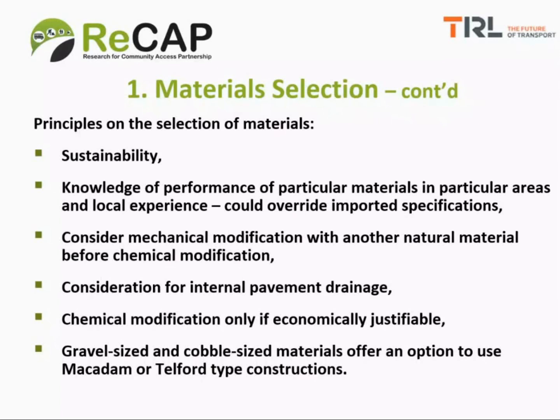And the third principle to bear in mind is that often if your materials do not meet specifications, please consider mechanical modification with another natural material before considering chemical modification. And the fourth principle is that where possible, consider the effect that the material will have on the internal pavement drainage.